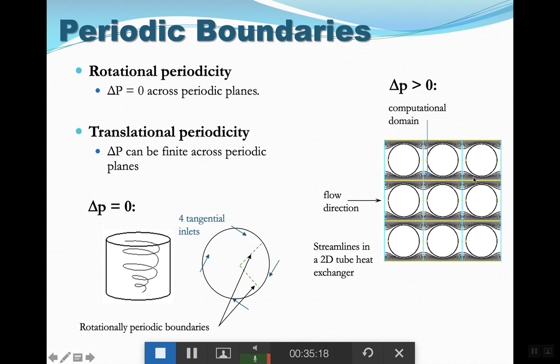Now you see this is a sort of geometry repeating itself. Your pipes, every 3 pipes on top of each other, is identical to the next 3, identical to the next 3. The only difference between these sets of three is that the pressure is dropping. So the pressure is changing by a constant number between each section.